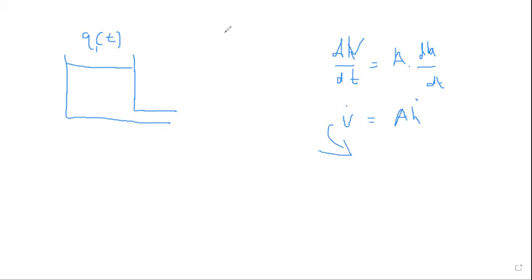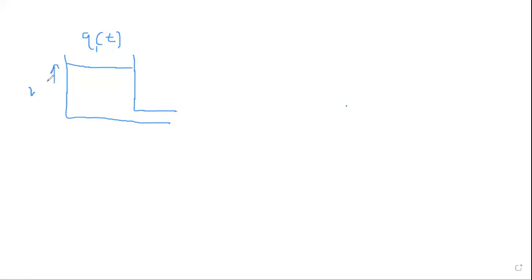Now we need this part here. So it's important that you write in the correct format, whether it's in the time domain or the spatial domain. At the time, the height here is also a variable, right? As the flow changes, the height changes. So you can write it as a function of time. You can get the radius of this part as r, and you can get Q2 as a function of time, right?